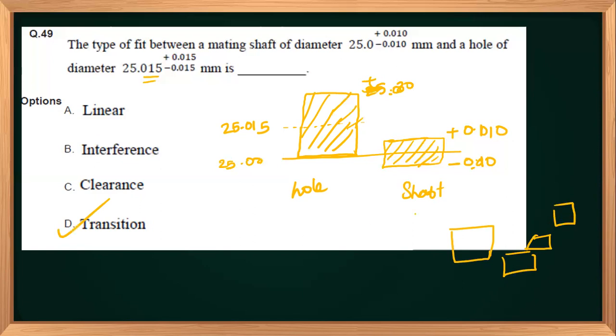If there is a marginal difference between this one and this one, only it will change this thing. If it is a clearance fit, it would be always interference or always clearance. But since sometimes it is interference and sometimes clearance, it's a transition fit. Suppose you have missed these things and you try to do them again, this is what you get if this is the line. Still you will see that it's a transition. I hope all of you get this.